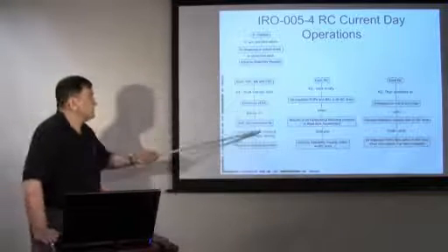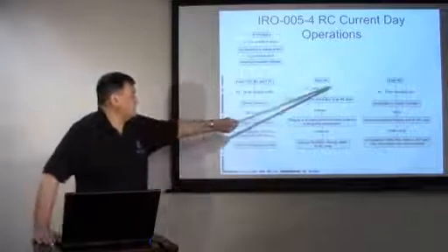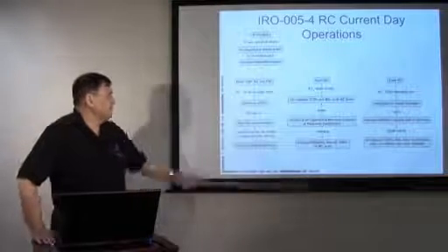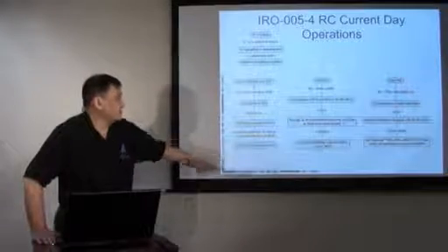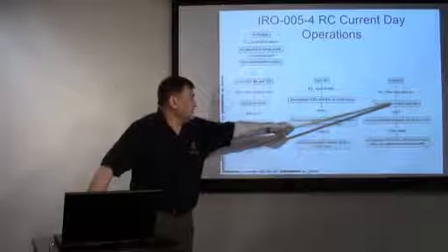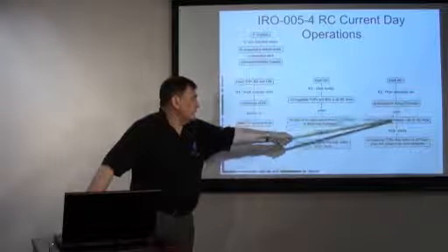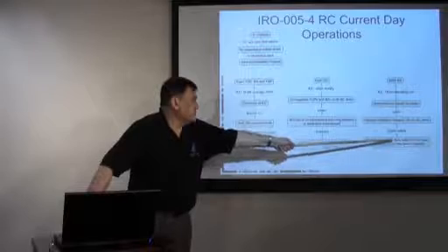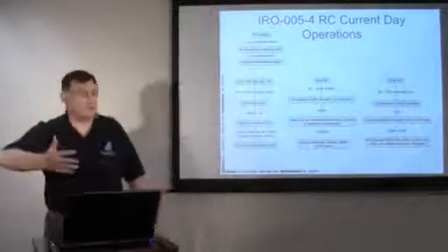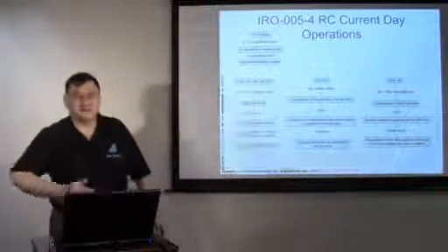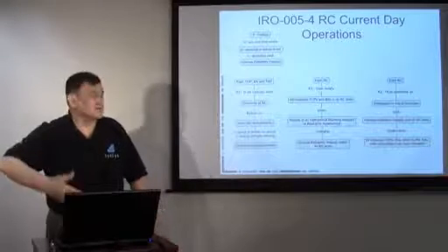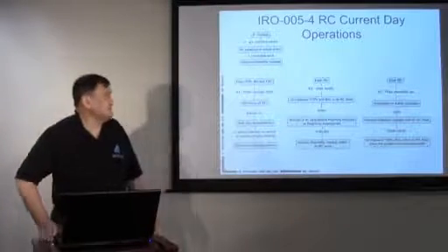But the standard here is very clear about it. The reliability coordinator will notify the impacted transmission operators and balancing authorities when the results indicate adverse impacts on reliability. And then the reliability coordinator that identifies the actual or anticipated condition will notify the transmission operators and balancing authorities when the problem has been mitigated. So clearly, after the problem goes away, the transmission operator and balancing authority can start shutting down the expensive gas turbines and bringing on the more economic remote generation, they need to know about it, and so that's what this standard here covers.